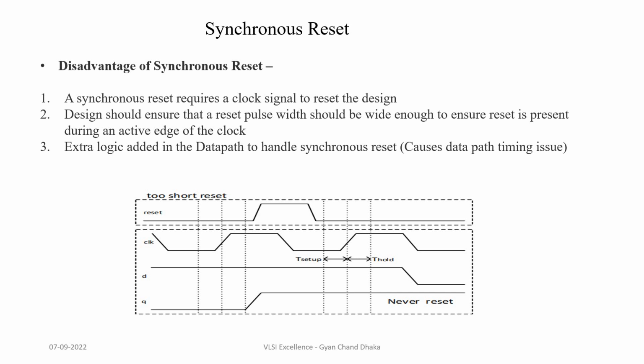If the expectation is to put the design into a known state even before the clock is available, it is difficult to do that with synchronous reset, or basically we cannot do that. So the disadvantage of a synchronous reset is it always requires a clock signal to reset the design.